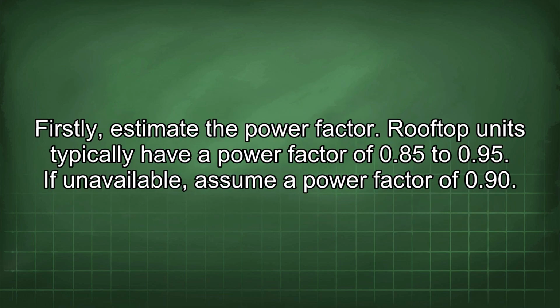Firstly, estimate the power factor. Rooftop units typically have a power factor of 0.85 to 0.95. If unavailable, assume a power factor of 0.90.